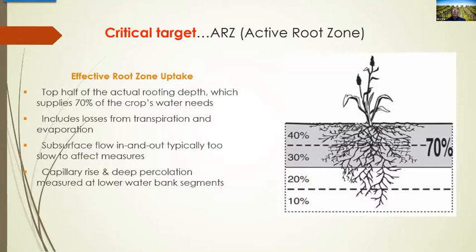Again, in a sandy soil, that wetted area will be narrow and long. So wherever that dripper's dripping in a sand soil, you can do any kind of experiment you want, but the best experiment is go to the beach. As the wave comes up on the shore and the water disappears, you know that there's no water holding capacity within that soil.